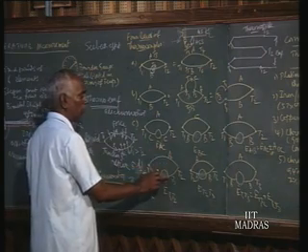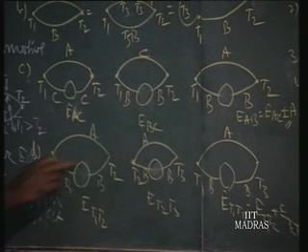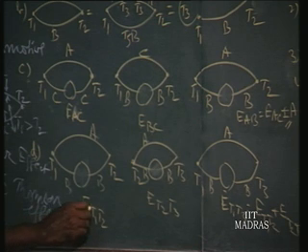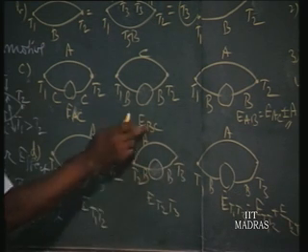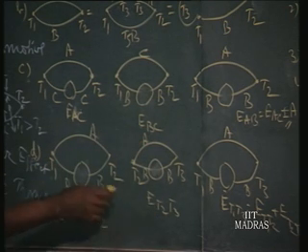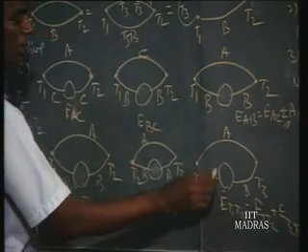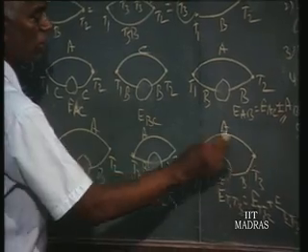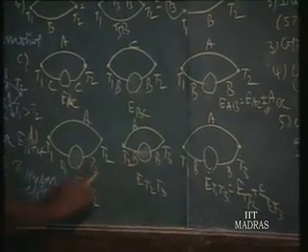Suppose we have the thermocouple pair A and B. First, the EMF developed between the junction temperatures T1 and T2, where T1 is larger than T2, is called E T1 T2. Then the same pair measured between T2 and T3 gives E T2 T3. Then the voltage developed between T1 and T3 is E T1 T3, which is equal to E T1 T2 plus E T2 T3.